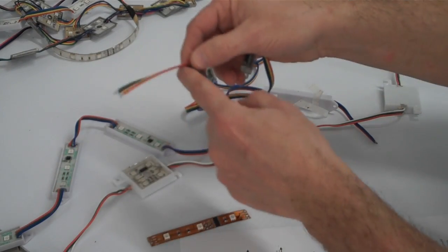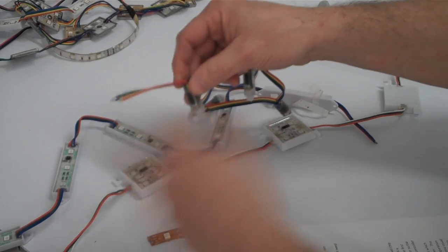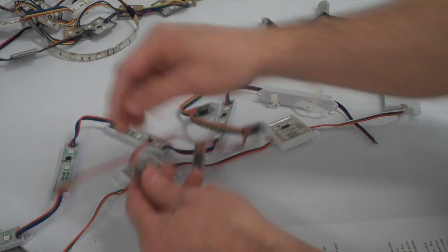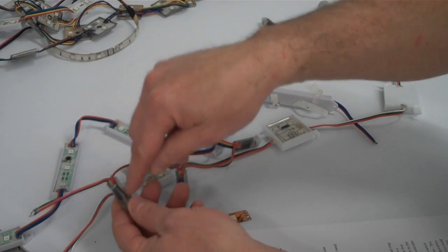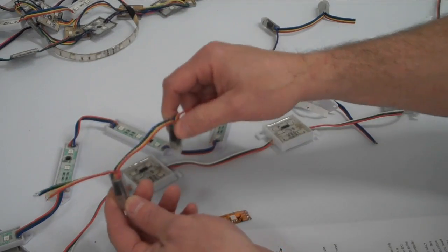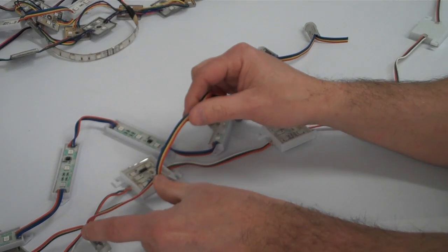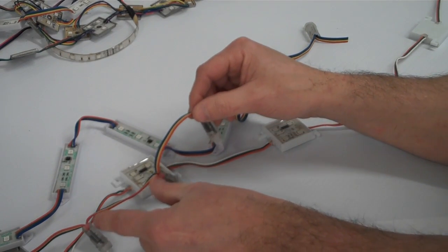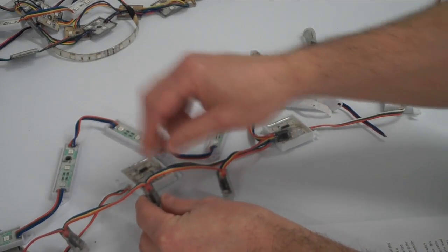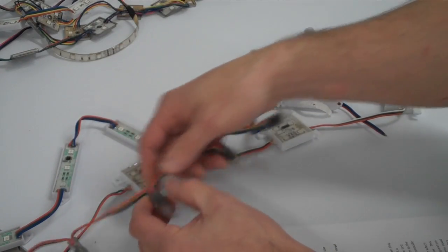For example, if you have your controllers way away from your first pixel, how do you make sure that the signal gets to the first pixel without getting corrupted? Now, as it goes to each pixel, that controller then picks up the signal, regenerates it, and sends it on to the next pixel. So, in general, assuming you don't have large distances between each one of these pixels, you can send the data for extremely long distances. What is generally the limit, and we will talk about this in depth later, is the power. You can only send so much power down these thin lines before it becomes an issue.